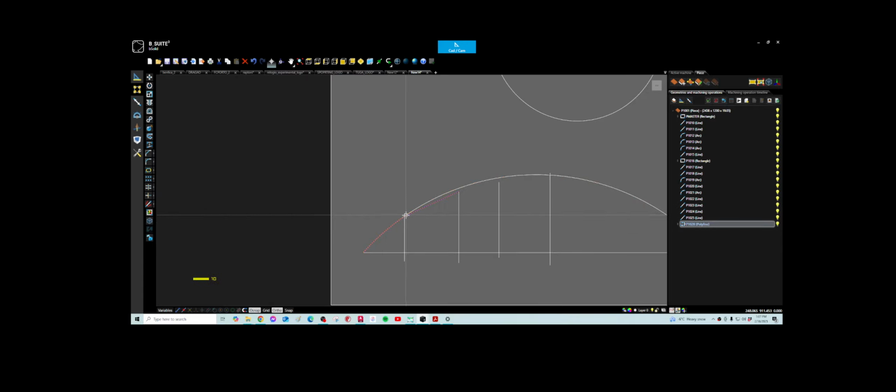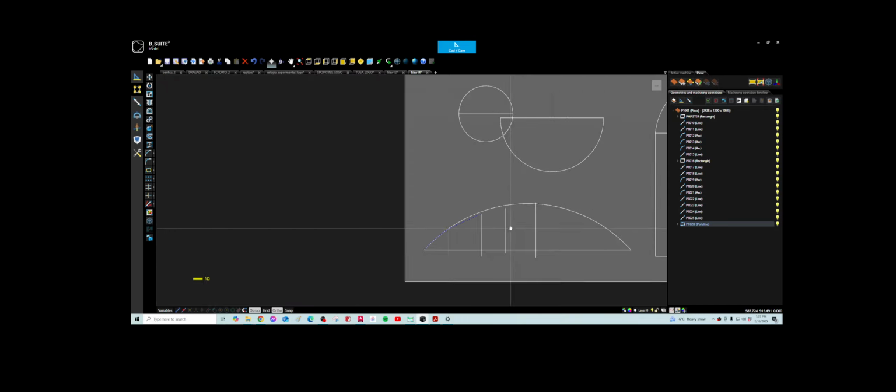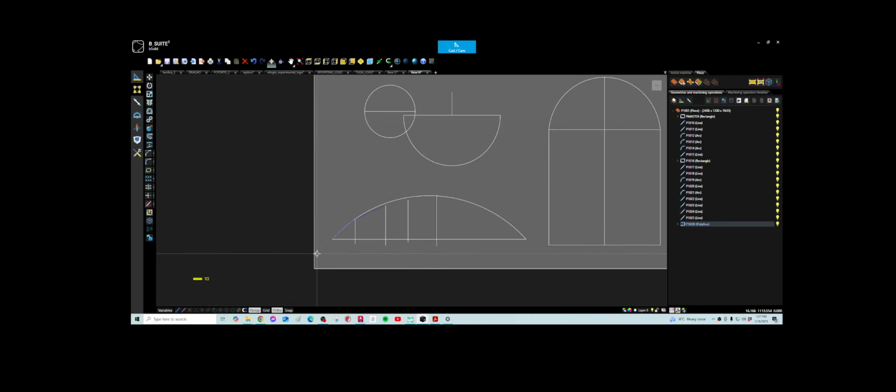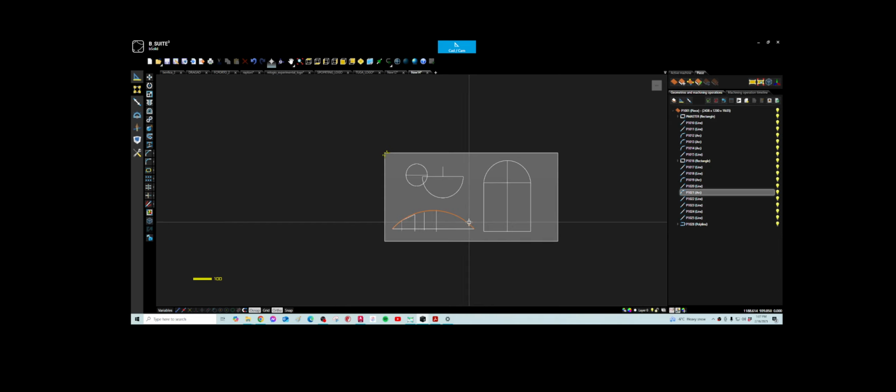You need to work your way around, and then what I do is I put a bit of cutting in the sheet sample, for example. I make a line with the template, and then I put a half millimeter or something, just cutting into the piece to see where the line is. And then because I make it in points, I will have to adjust a little bit accordingly, whatever I need. Well, I just extend a little about this.